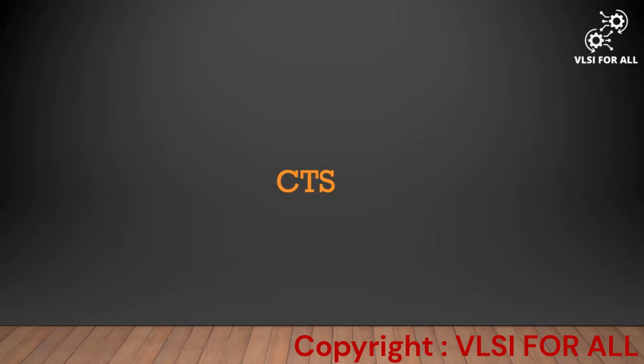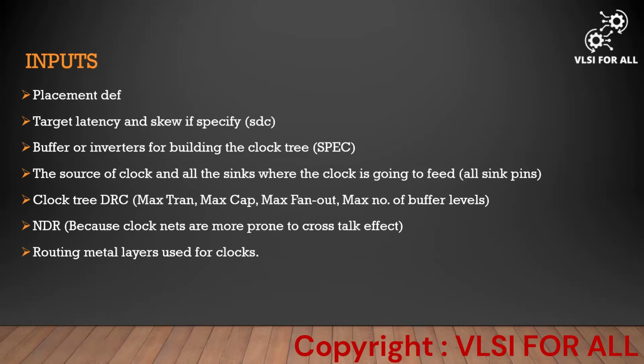Now moving to the next stage, CTS. In CTS, the inputs are the placement DEF and the target latency and skew, which are in the SDC. And the next one is the spec file. In this file, we have clock buffers, clock inverters, and clock cells information. Along with that, we have max transition, max cap, and max fanout information, and mainly NDR rules. All this information will be present in the spec file, and also the routing materials which we have to use for the clocks.